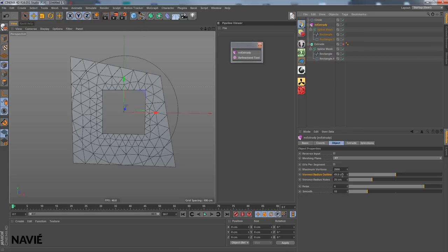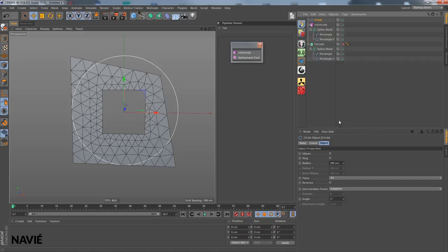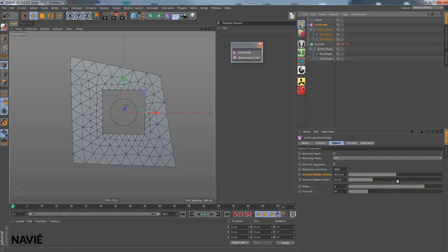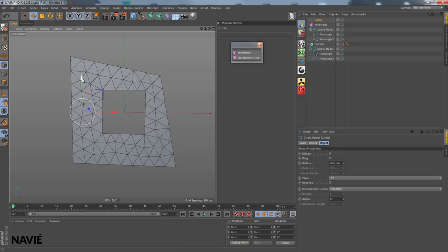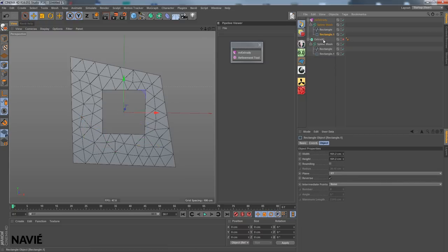And in order to show you what the radius here is really standing for, I'm creating this circle spline, and let's put this up again so it'll be a little faster. And now if I put this here, you can see that the circle is enclosing this polygon star almost exactly. So this is kind of the radius the setting is actually controlling. At least it is the maximum size, depending on the domain that needs to be triangulated. Of course, triangles could be smaller, but it will never get bigger than this.